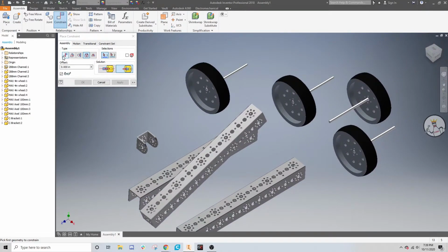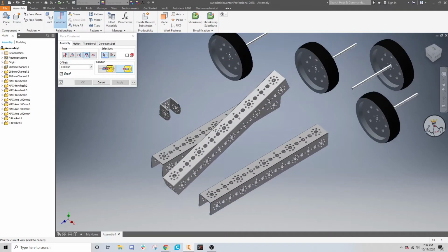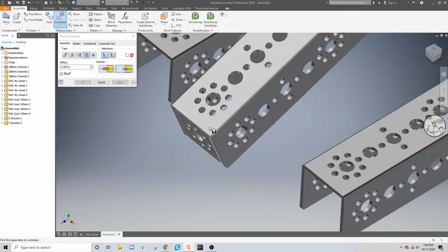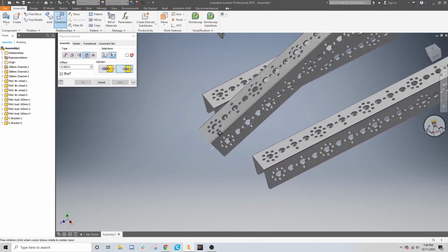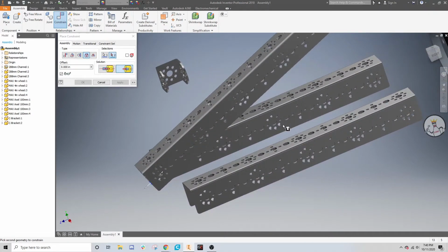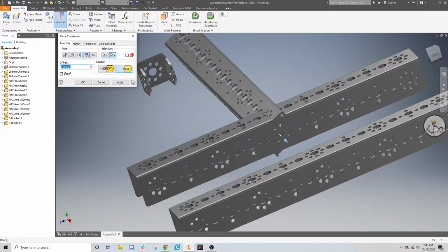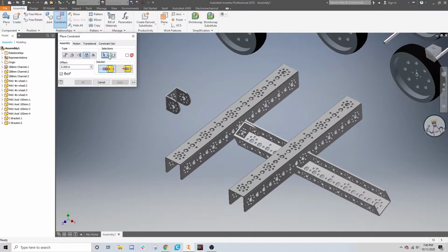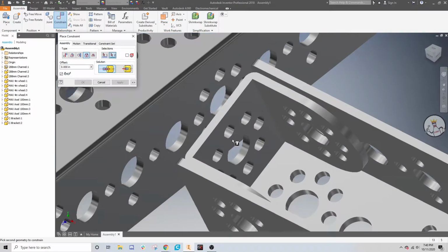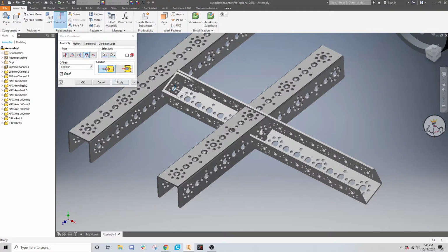So from there, that's with axles and wheels. You can also do it with all the circles that are on the Tetrix channels. And I'm going to place this right here and change the option so it's pointing the right way. Actually, I want to show another constraint later, so I'm going to change this. As you can see, I just click on these 2 mouse icons and it deselects what I've already selected. So I'm going to select that and then apply.